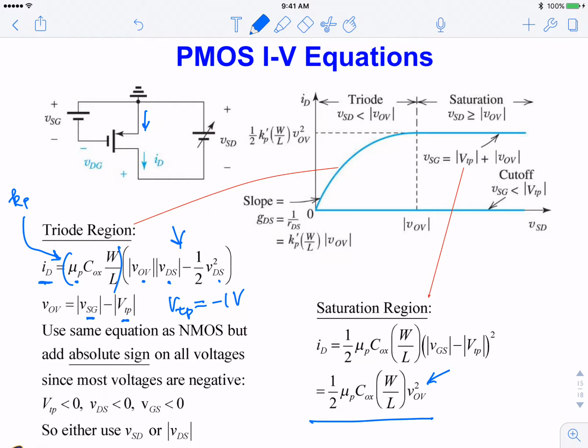It is used for circuit design that actually produces circuits as complex as millions of transistors, and tape out to have that fabricated into a real circuit. In Cadence, you draw a layout, which gives the physical size of each transistor. And usually you'll find PMOS to be about 3 times wider than NMOS.